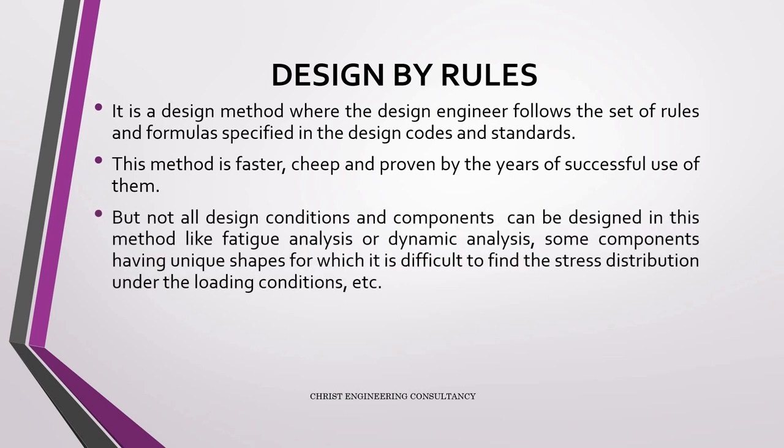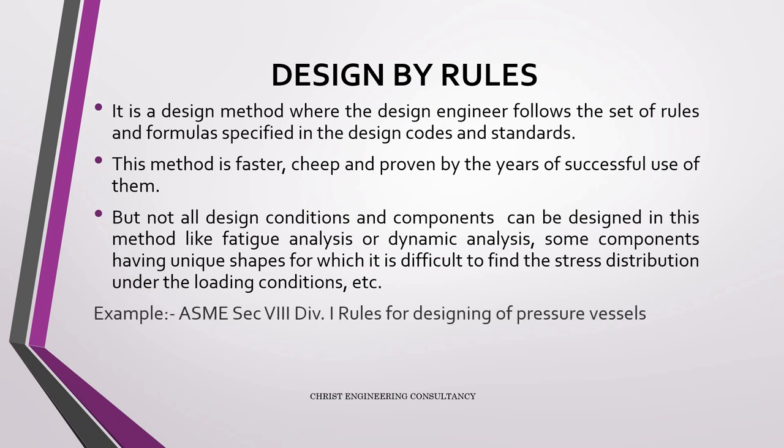But not all design conditions and components can be designed in this method, like fatigue analysis or dynamic analysis. Some components have unique shapes for which it is difficult to find stress distribution under loading condition, etc. Example, in ASME Section VIII Division 1, the design by rule method is followed.